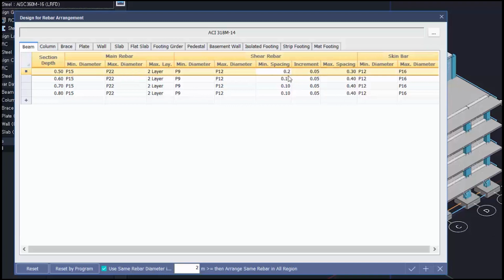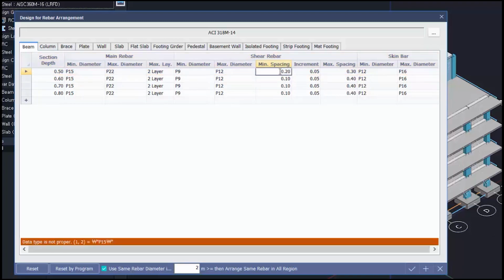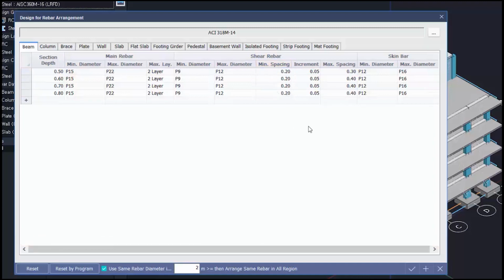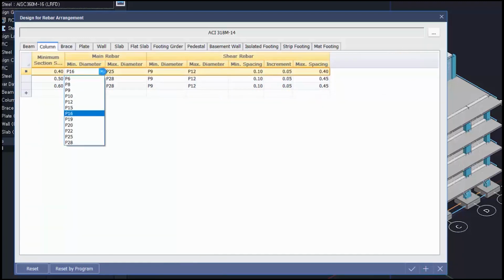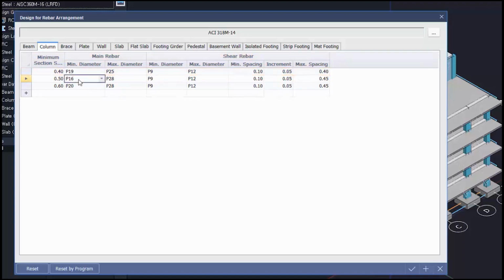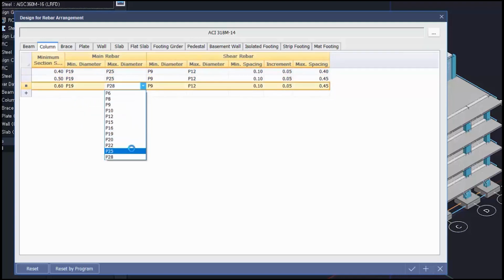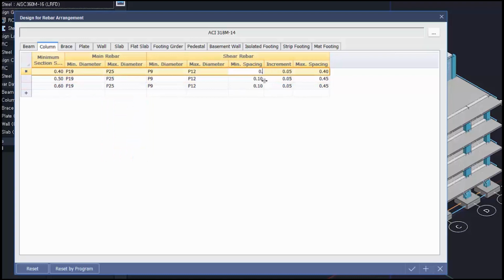Engineers can set boundary for the main and shear rebars of each member. It is automatically designed within the category. The principle of automatic rebar is simple. It is to determine the final NG or OK after the software tries to calculate the reinforcement from the minimum dia rebar to the maximum dia rebar.